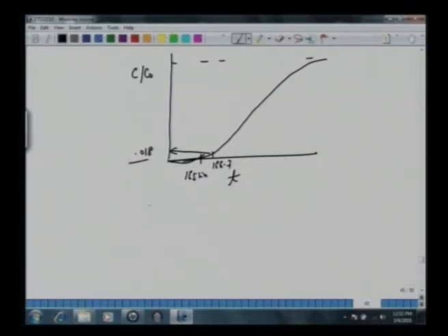So this is 166.7. That means, as per our definitions, we can say that very close to this breakthrough time, TB is 165 minutes. So going back to the previous data, at 154 there was 0 response, then at 167.7 we have 0.018. One can do this interpolation to obtain that the breakthrough time is around 165 minutes. Okay, and then at 350 minutes